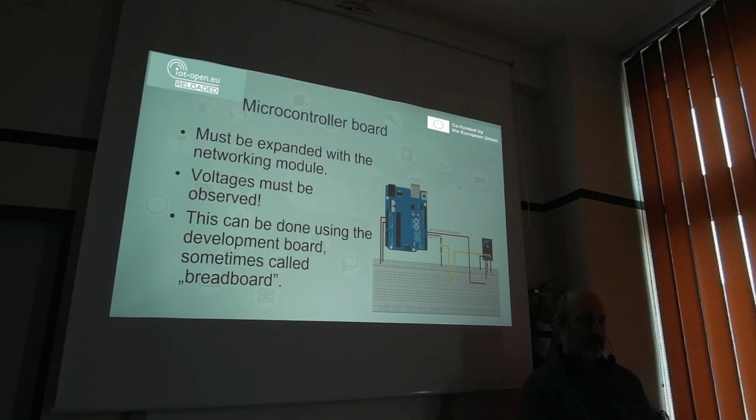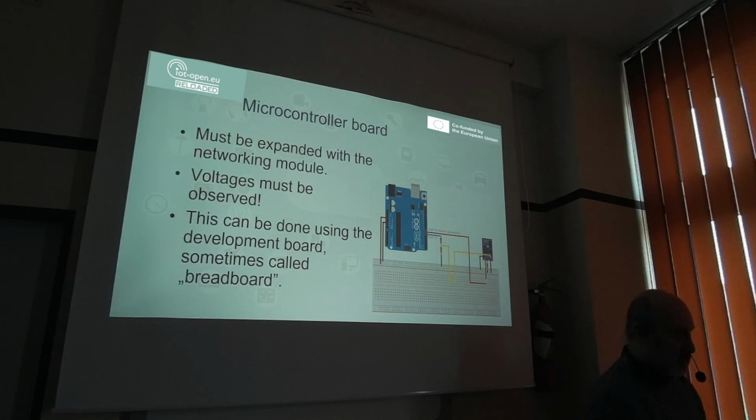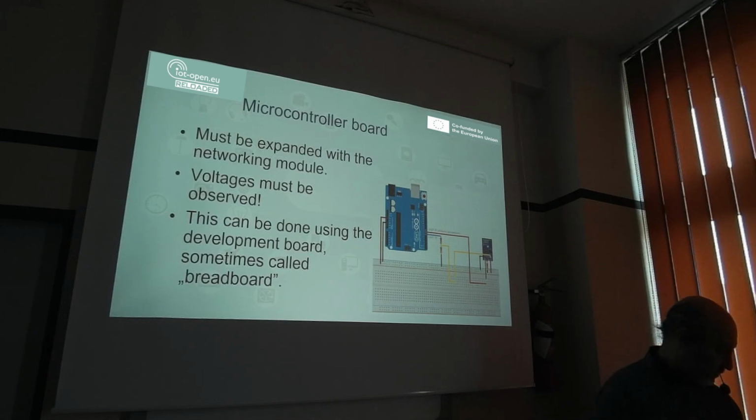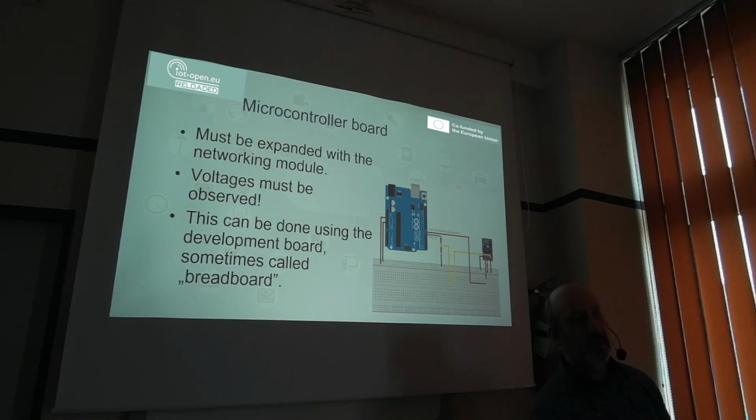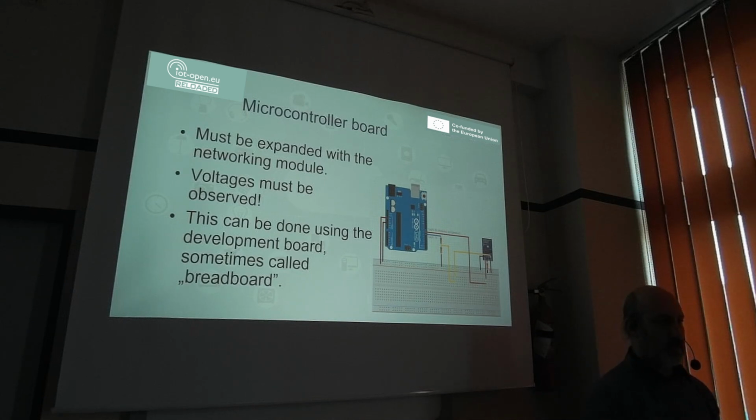You can use a microcontroller board like Arduino here. So you take a ready microcomputer, and it must be expanded with a networking module. So you connect to the Arduino an ESP01 that works as a Wi-Fi module that enables you to connect your Arduino to a Wi-Fi network. What is important here, different boards, different elements can have different voltages.